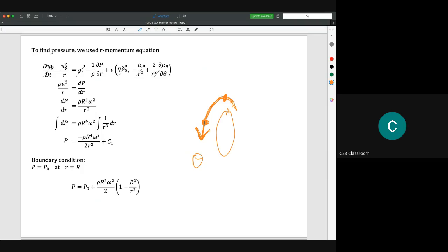So it is useless for us to use the theta axis to calculate the pressure, because the velocity change is zero, which means the pressure gradient is also zero. But we have a lot of streamlines there, and the velocity here, here, and here is changing, because the greater the value of r, the velocity goes near to zero.